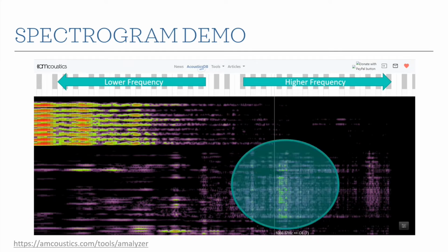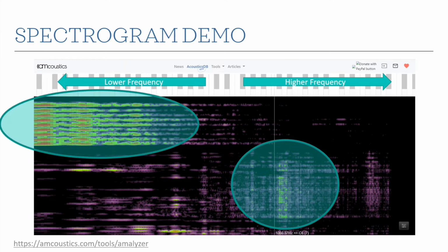In this case, I think I was tapping a pencil lead or something like that on my desk, or tapping my nails. So this is a very high frequency clicking sound, and that was this first circle here. Then this other one was me pounding my fist, thumping. So you can see the sound looks different, and that's the different frequency content. That's the same kind of thing we're getting with those graphs for the STC and IIC tests.